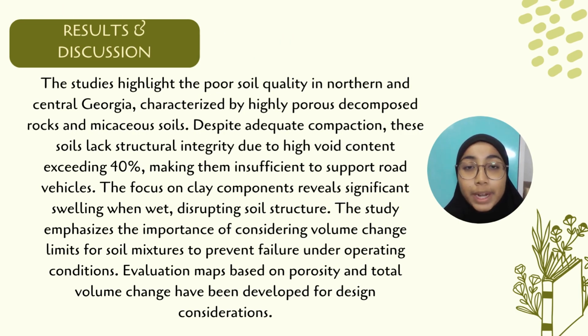Moving on to the results and discussion part. The study highlights the poor soil quality in northern and central Georgia, characterized by highly porous decomposed rocks and micaceous soils. Despite adequate compaction, these soils lack structural integrity due to a high void content, exceeding 40%, which makes them insufficient to support road vehicles.